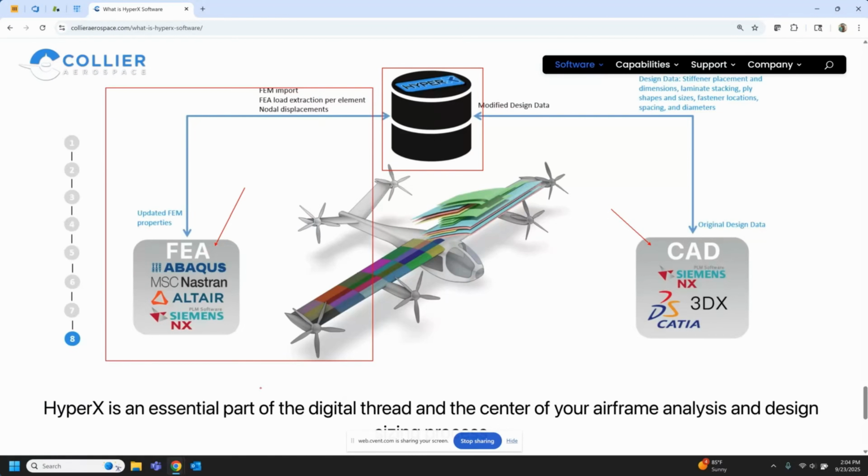And it will automate the sizing process of that finite element model and spit out those updated FEM properties into an updated run deck that you could then run through FEA or perhaps pull back into your pre or post, whatever you might want to do with that. Like I said, we've been doing this pretty well for on the order of 25, 30 years now.